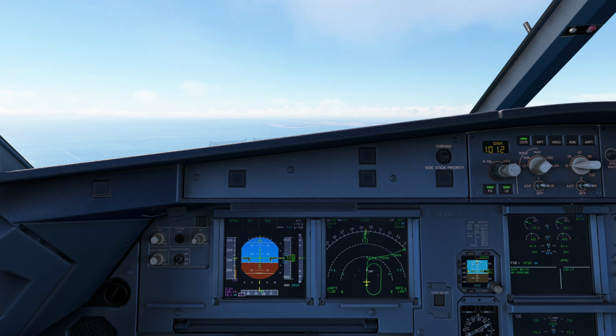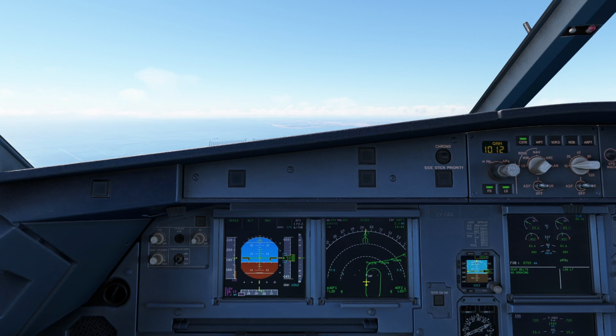Make the FDs, flight directors, off, and then disconnect the autopilot and land manually. Never do the autoland, as briefed already, due to some items as well as rollout guidance. And finally, be aware of possible lateral displacement at minimums.